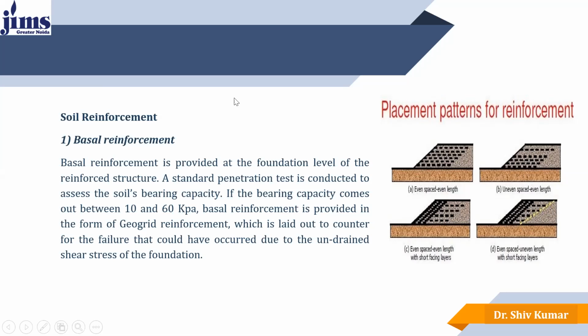Basal reinforcement is provided at the foundation level of the reinforced structure, where the standard penetration test is conducted to assess the soil bearing capacity. As I have mentioned previously, these geosynthetic materials can be used to increase the bearing capacity of the soil. Where the soil bearing capacity is comparatively low, we can provide this kind of soil reinforcement.